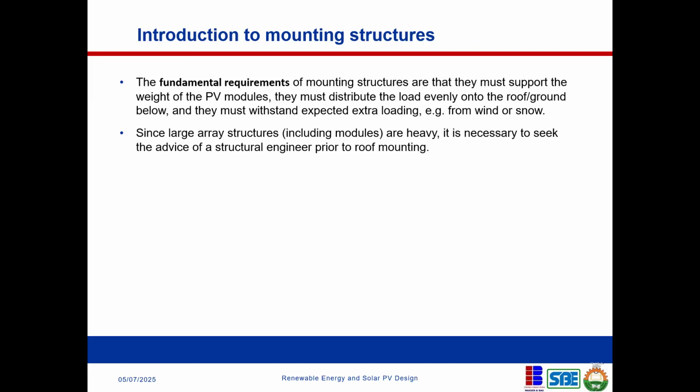Sometimes your solar PV system can produce a higher voltage. If you allow that higher voltage to go into the battery, it's going to damage the battery. So what the charge controller does is that it regulates the voltage that goes into that battery. If your battery is rated 12 volt, it makes sure that only 12 volt gets into that battery. If you have excess voltage, it converts it to current.